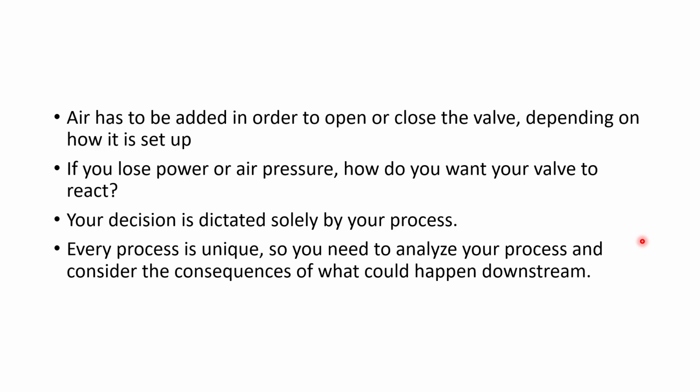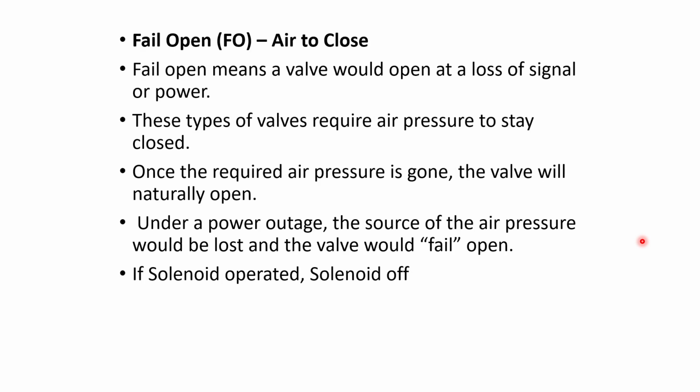It is important to remember that valves are generally pneumatic, meaning that their function is based on air pressure. Air has to be added in order to open or close the valve depending upon how it is set up. If you lose power or air pressure, how do you want your valve to react? Your decision is dictated solely by your process. Every process is unique, so you need to analyze your process and consider the consequences downstream.